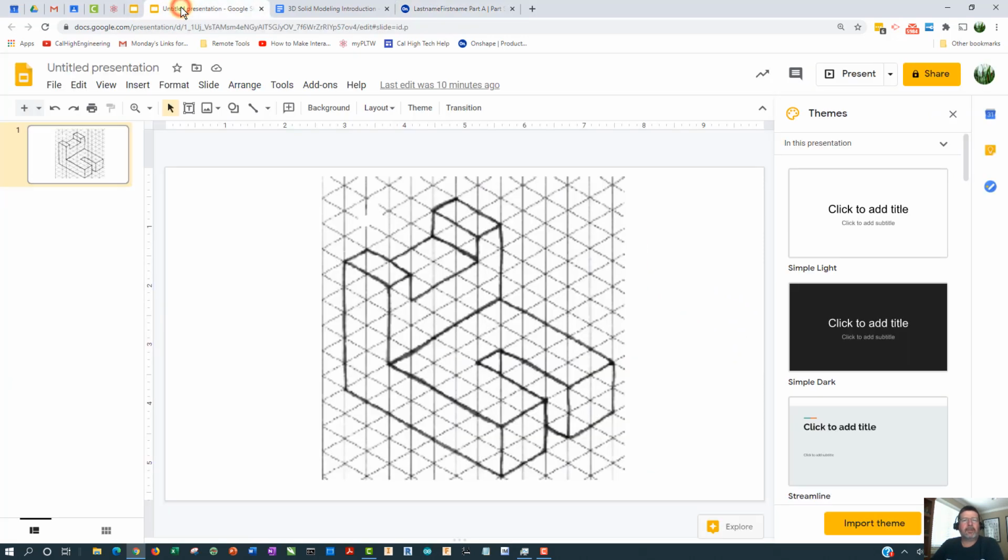The part we're going to make is right here, and we're going to make it by first making a two-dimensional closed sketch, which is this sort of L on its side, and then we're going to do what's called extrude the rest of it out 5 units. This is 5 high, 7 wide, 2 high here, 5 back, up 3, back 2, so we can make this two-dimensional sketch pretty easily. And then we're going to do an extrusion back here, and I'll show you all that stuff.